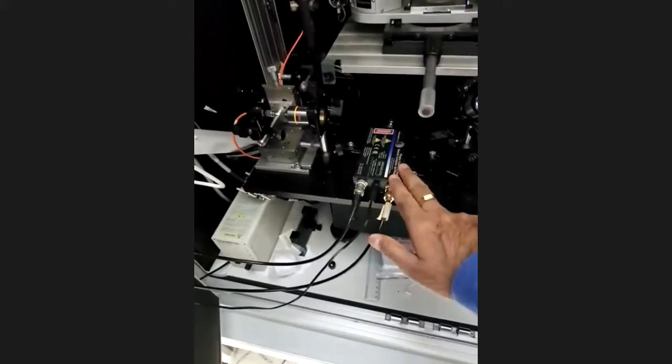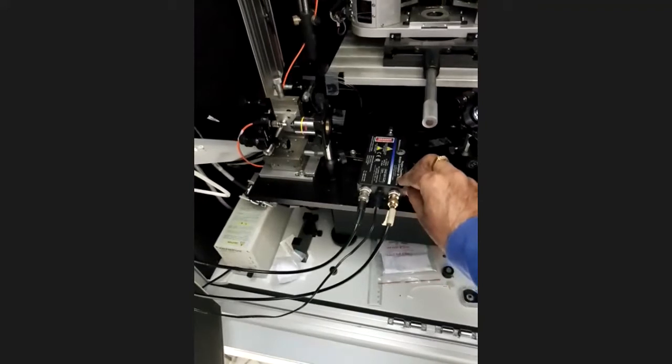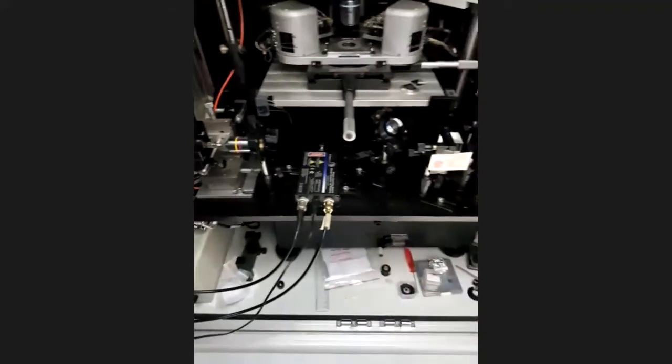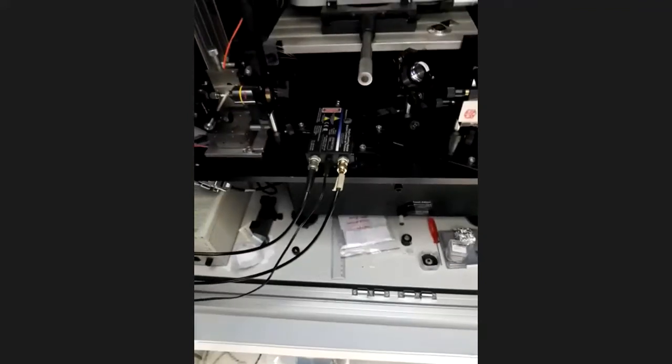Okay, something like this. So the shiny thing which you see, that's a silicon chip which is used as a photodiode. Okay, and I showed you the avalanche photodiode, which is basically a photodiode which is reverse biased. So this is an avalanche photodiode which is cooled. So this entire thing is to cool the photodiode to lower temperatures so that the thermal noise will be very weak.